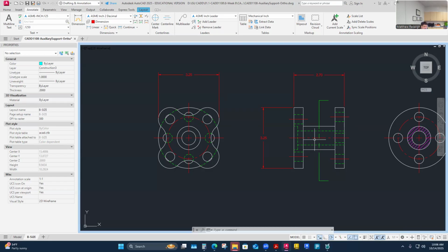That's where GD&T land comes to save us and says, actually, I can control how cylindrical the bore is, on the outside or the inside, or whatever is going to be best. I can place some symbology that is telling the person that's going to make this that not only am I pulling my dimensions off of a center, but I need you to control how true and straight that center is.